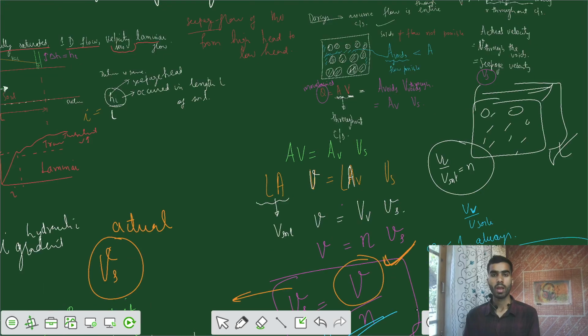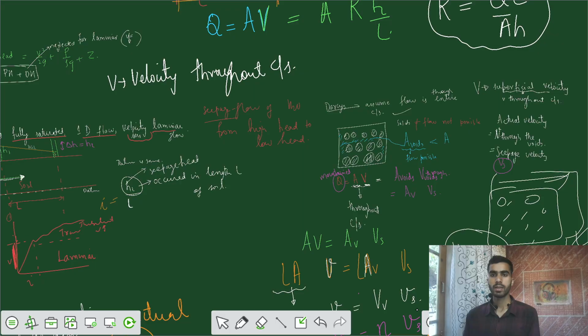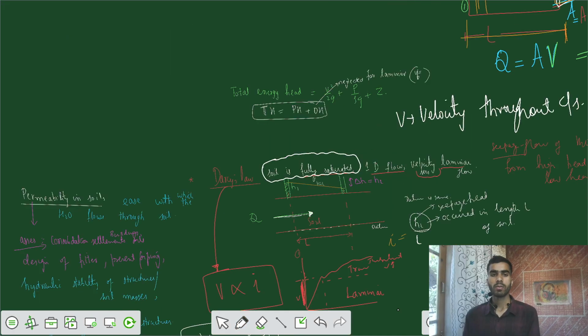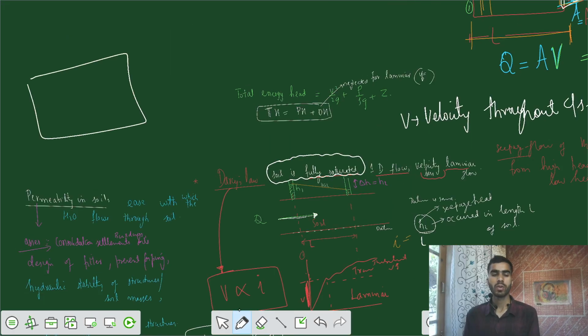Okay. Now that was all about Darcy's law. Let's try to revise all of the stuff for Darcy. Darcy said that our soil should be saturated. That means once the soil pores are saturated with water, and we apply some water from the top, that water is allowed to leave the soil, because the soil pores are already saturated, so it would be collected from the bottom.